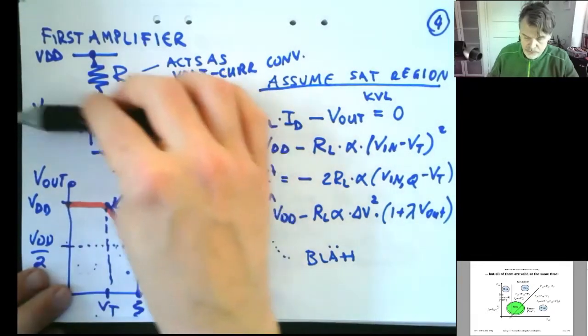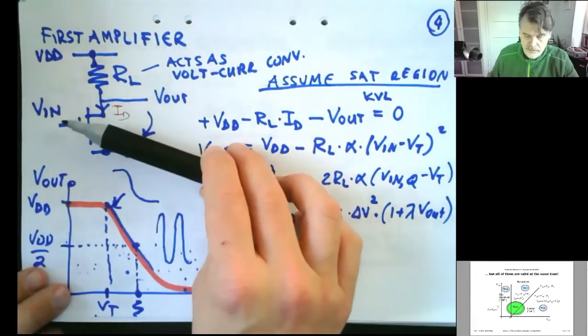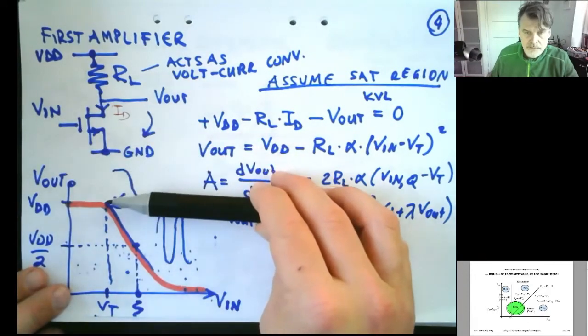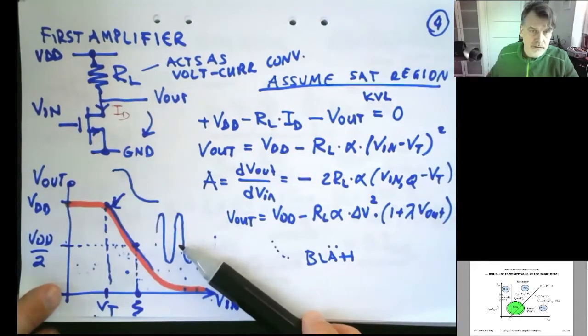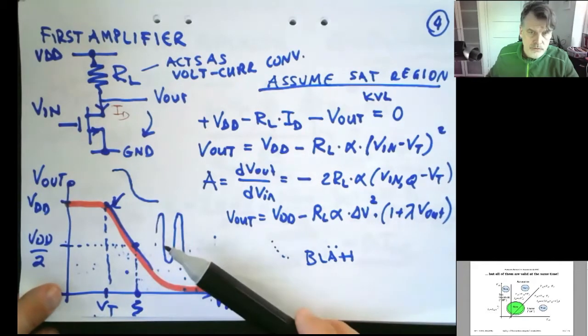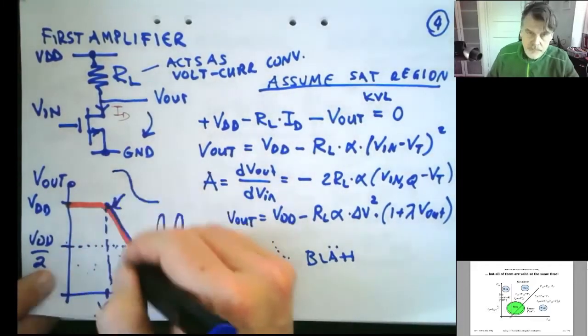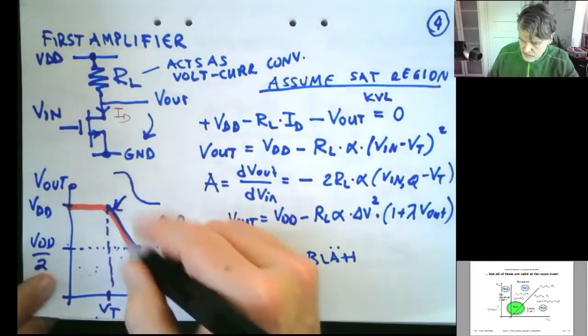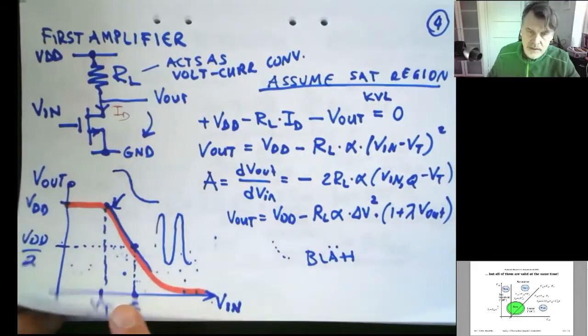So I really have to push down my input voltage towards ground here, towards the threshold voltage, then I get the highest gain. And as you notice, then that really contradicts this decision here to some extent. It's not the whole truth, but it's a sort of part of the truth. The truth is a little bit hidden in the way I've drawn the diagram here, but there is a slight contradiction here at least. That's the result.